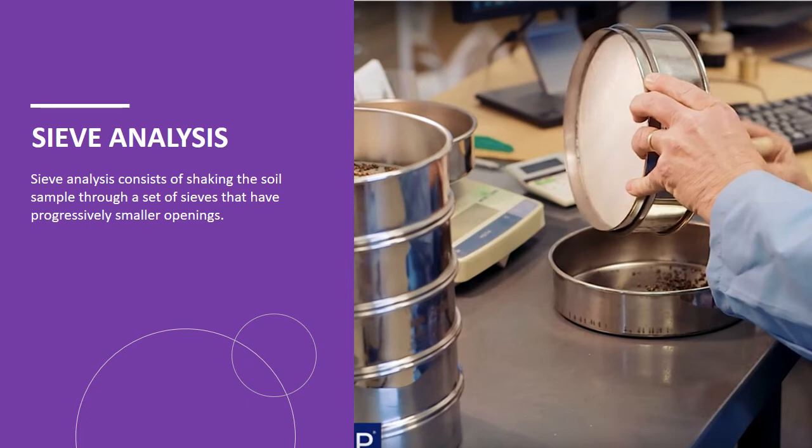Sieve analysis consists of shaking the soil sample through a set of sieves that have progressively smaller openings. Each of these sieves is stacked against the others, with progressively smaller openings.